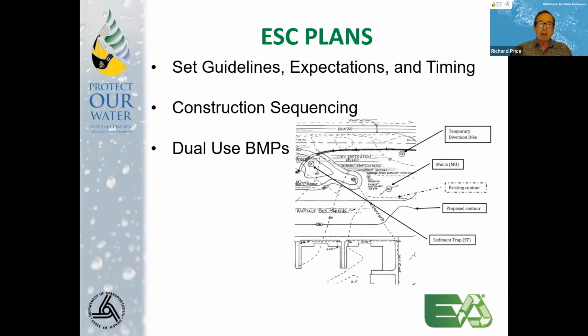One of the advantages that I always see in this is that I'm constantly struggling with designing and trying to get the contractor to build infiltration BMPs like rain gardens without building them and using the rain garden to control construction stormwater and putting a lot of sediment into those soils that are designed to infiltrate. So by waiting until the very end, once the site is stabilized and then building your infiltration BMPs, you avoid any potential for construction input to it. So always a possibility.